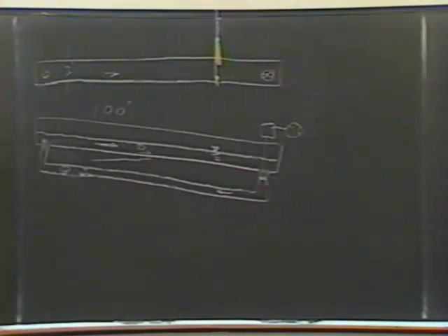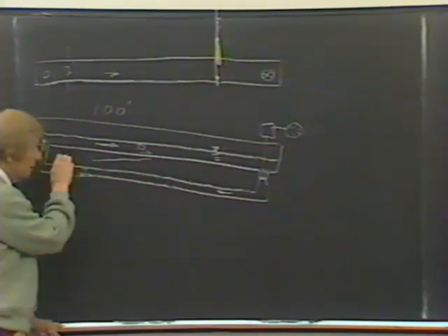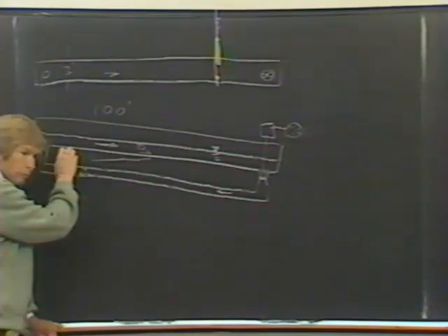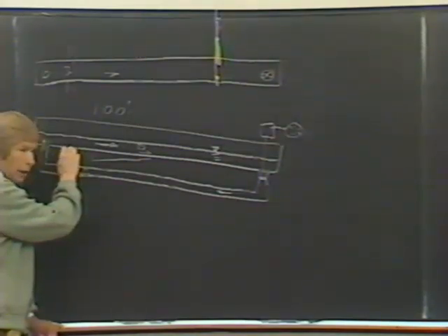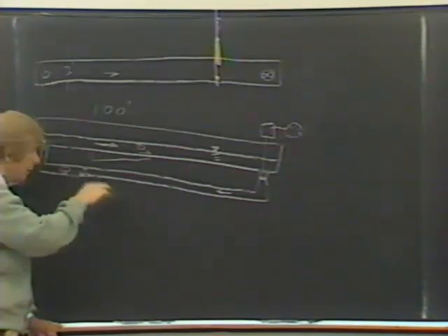The 1 foot depth was a compromise between the need to measure and depth. The method of operating this for deposition studies is to fill the flume with salt water so that you have cohesive particles, then bring in a sediment and add it to the flowing water, or if you have all the material deposited, increase the velocity to